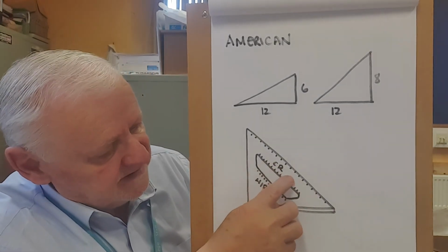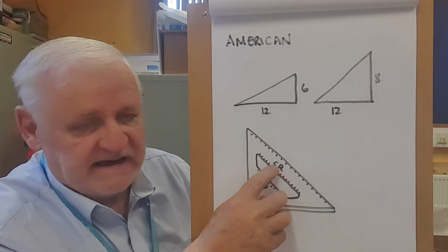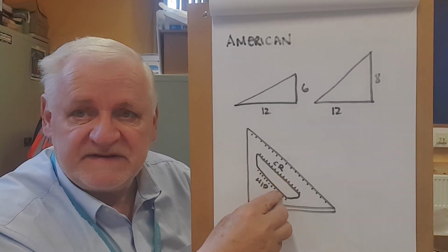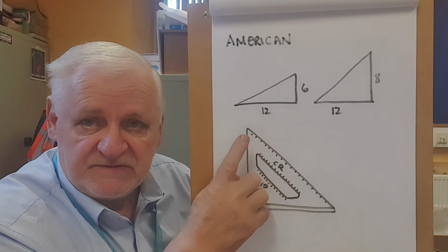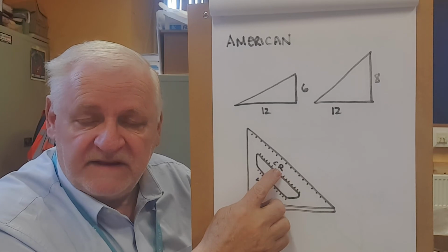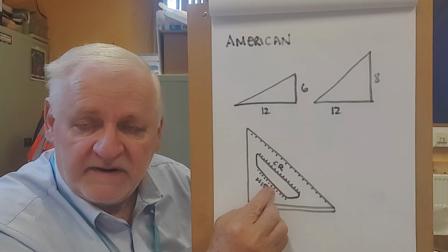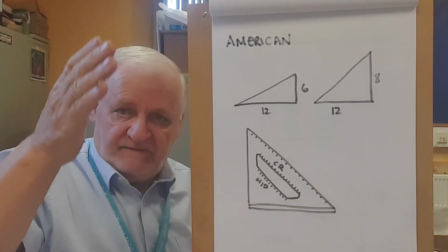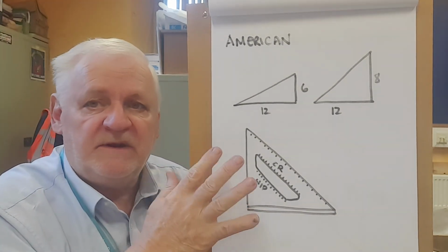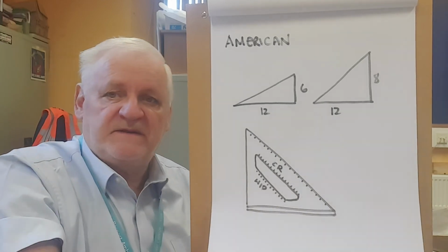And you say, well, that's good for the common rafter. What about the hip rafter? Well, they're on here. So if you're on a 6 here, then you look at these numbers and you adjust it slightly till you find number 6 on here. So if you're going to be on a 12/6 roof, you go 6 there and you go 6 here. These will be the common rafter shape, the vertical and seat cut, and these will be the hip angles, obviously for vertical and for seat cut. It doesn't work out the length. It only works out the angles. So is that okay? That's the pitches. It works out the pitches.